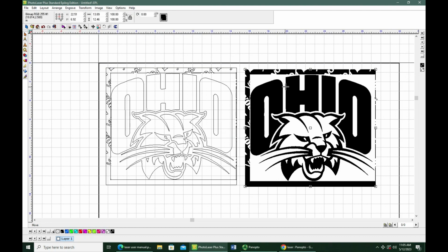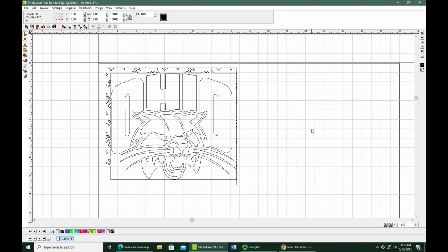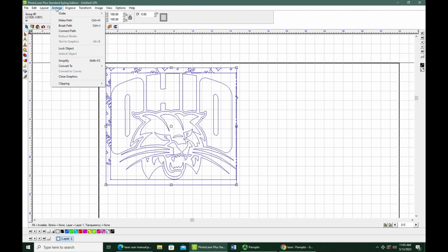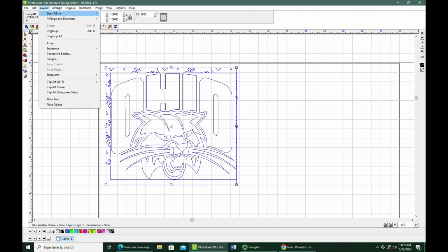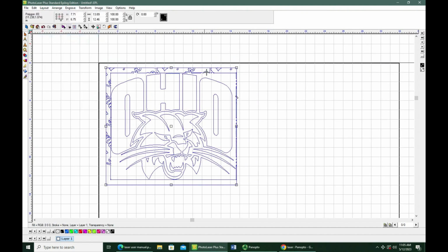We can also clean it off right here. I'll show that first. So if I have my image, I'm just going to highlight everything. I'm going to arrange, go to layout, ungroup all. That's going to ungroup all the individual paths, and then I can just click through here and delete all of these, and you can see some of them are in large chunks. There's also a little relic right there. Other bits are in little small pieces, so it's easier just to window it open, and you can easily step through and delete all of these.